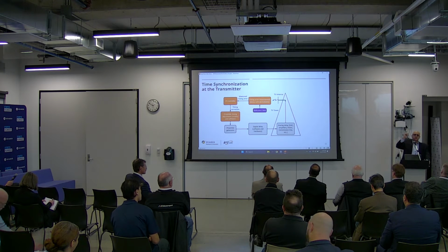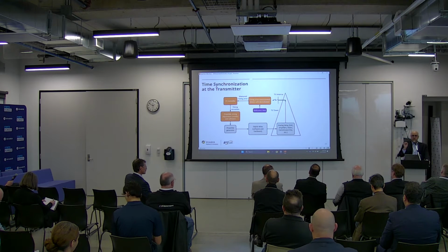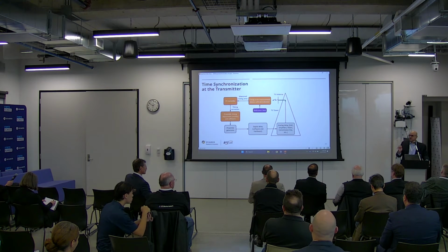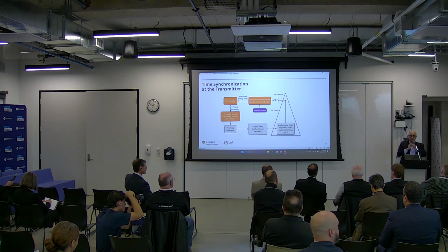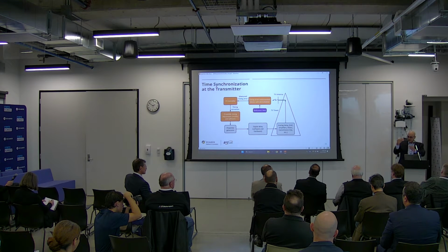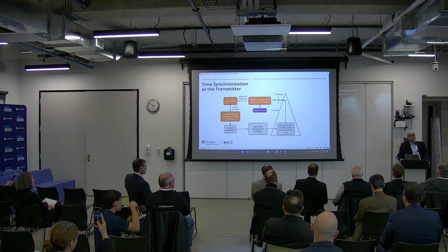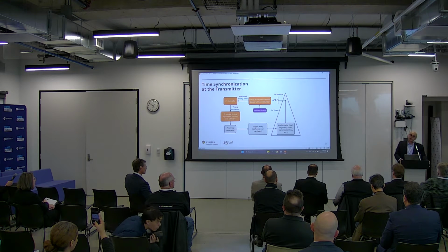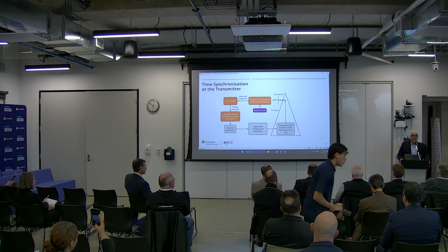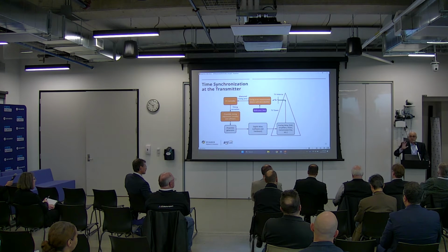So we have a detector, a sensor, that actually looks at the transmission that comes out of the transmitting antenna, decodes the message, and by correlation it finds the time of arrival, looks at the time, and then uses a reference time. As Sam Anthony mentioned, we are using GPS here, but it doesn't have to be GPS.